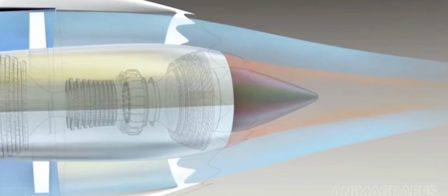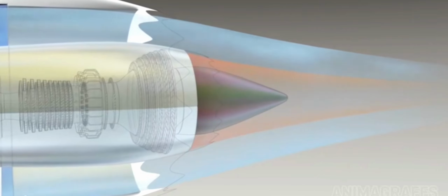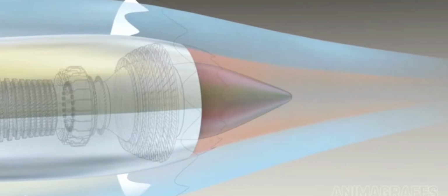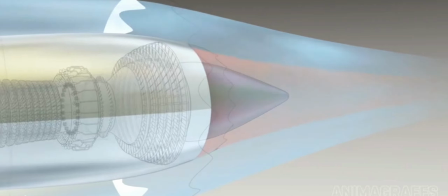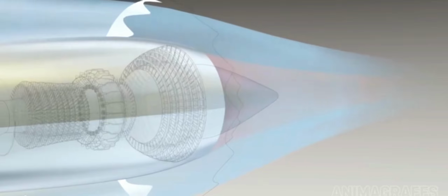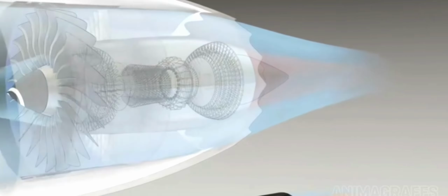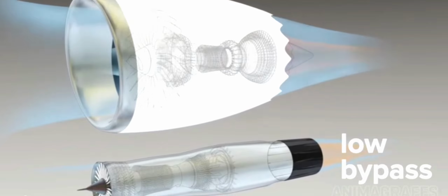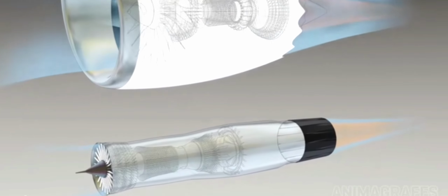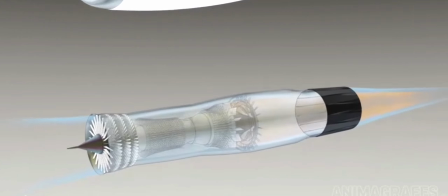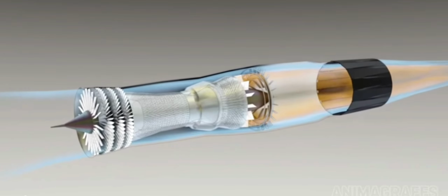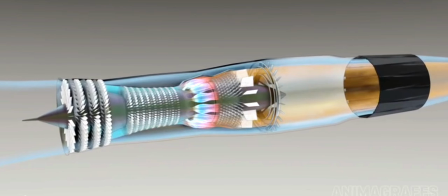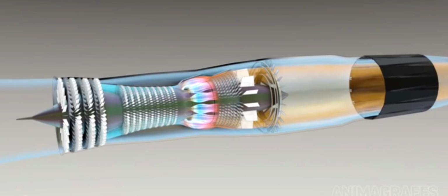Exhaust velocity is a major factor in jet engine noise. High bypass engines surround fast-moving core exhaust with large quantities of slower-moving bypass air for quieter operation. Military fighter aircraft use low bypass engines, which are more compact, have high power-to-weight ratios, plus supersonic and afterburner capabilities, in exchange for things like poor noise control and high fuel consumption.